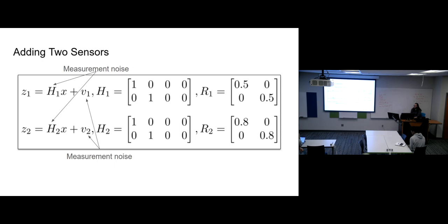The analogy I would use is overtraining in machine learning, where you train it on too much of the same data, so it loses the ability to generalize. Sometimes with too many sensors, you get snowballing. So I guess yes and no, and that's the art of Kalman filtering: figuring out what you need and how to model that. So it depends on the situation.